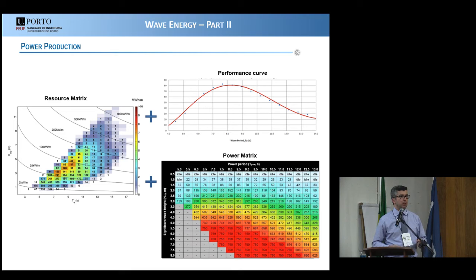So it is possible to tune the device by changing the inclination to have the device working properly for the wave conditions we have in a specific moment, because we cannot control the wave conditions, but we can at least try to adapt the wave energy converter to have the highest absorption of energy. In other cases, it is possible to change the weight of the device by putting some extra water ballast to change the response of the device, again with the intent to put the device working well for the conditions you have at that moment.